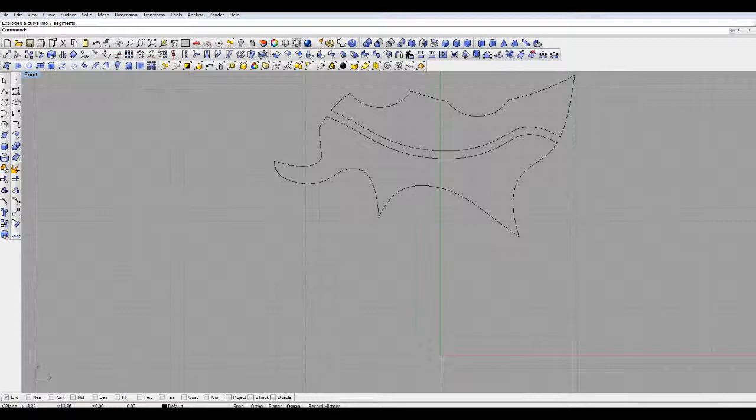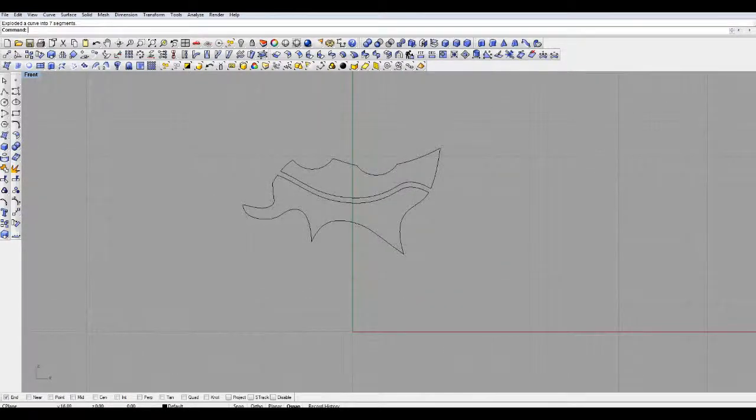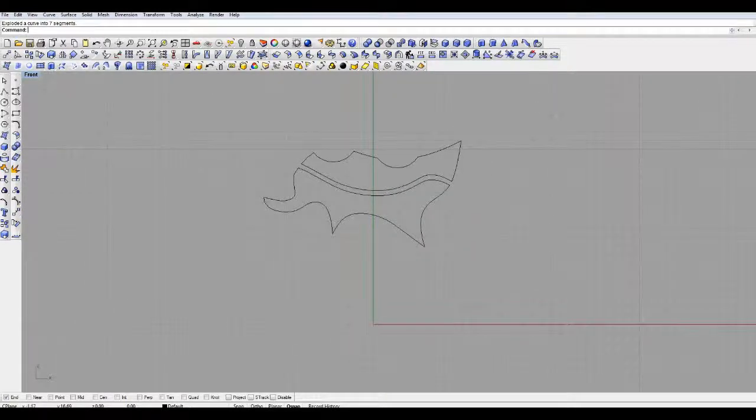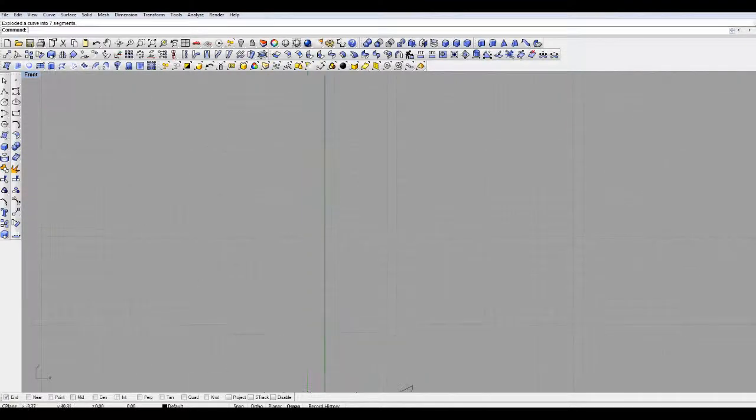So another useful command that I like to use in conjunction with these other two, especially if I'm trying to get a certain shape and I don't really know how I want to manipulate it yet, is actually going to be this one here. Control points on. So let's use a simple shape for the sake of demonstration here. I'm going to draw a circle, click my object. Clicking control points is going to turn on all of the individual vertex points that it assigns to the shape. So when you do that, it has 1, 2, 3, 4, 5, 6, 7, 8 points that it's assigned to this circle.